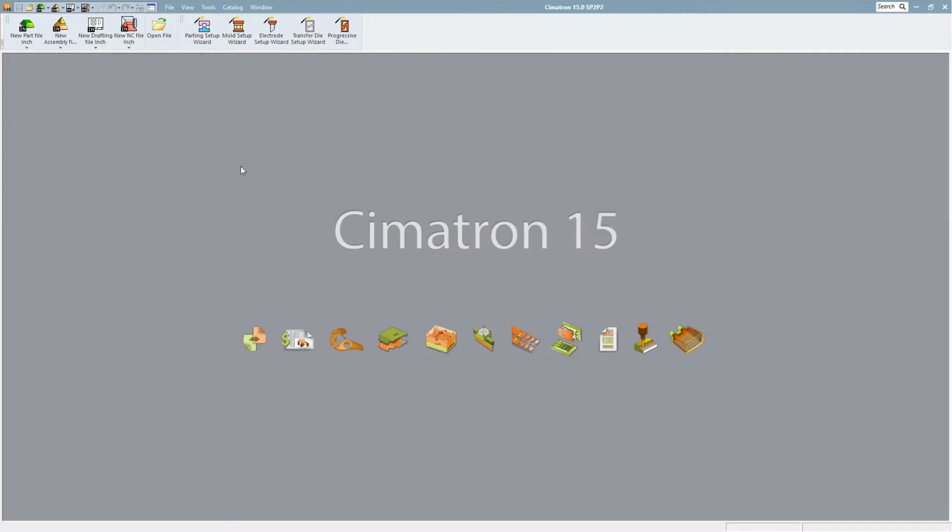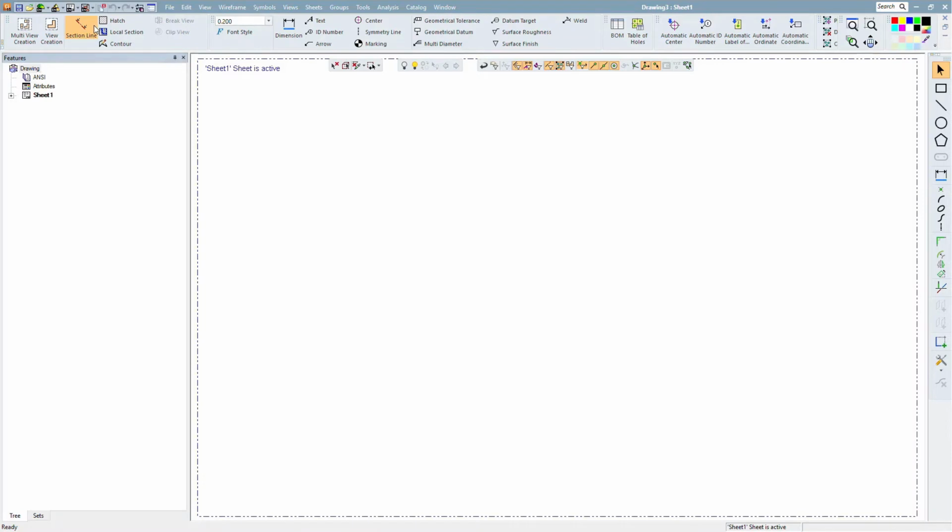Let's jump into the software and start a new blank drawing in inch units. Now the drafting tree on the left shows right at the top the current drafting standard, and in my case it's ANSI. And that's not because I selected to create an inch drawing. The drafting standard and the units are totally unrelated. It's because my drafting preference is set for ANSI.